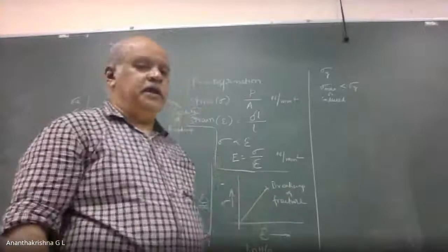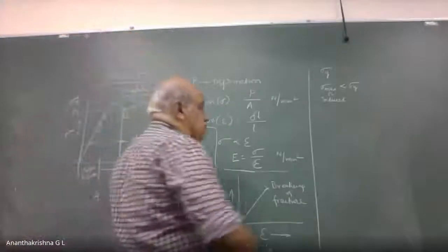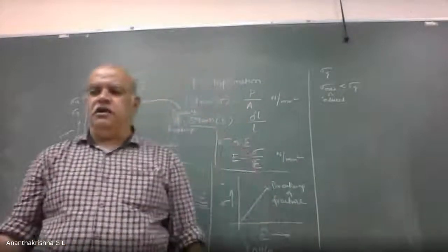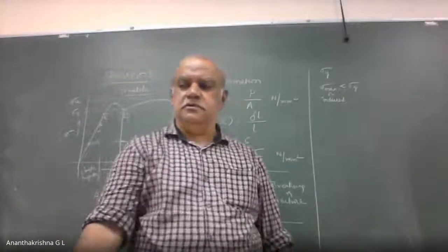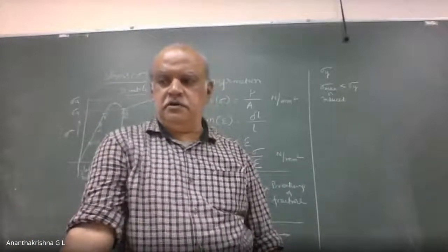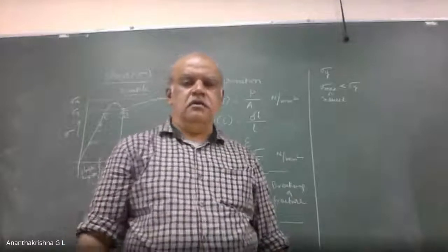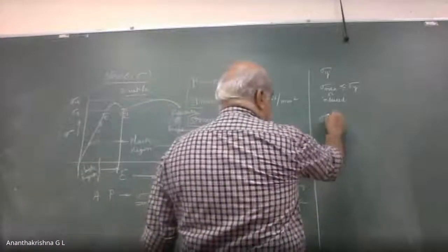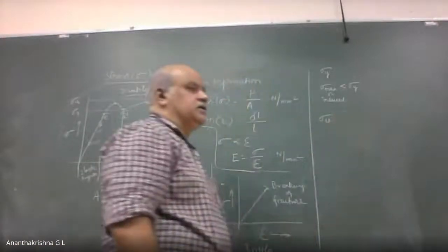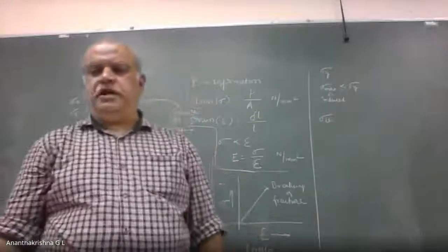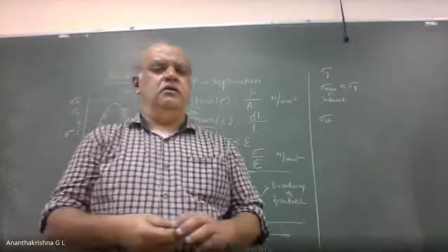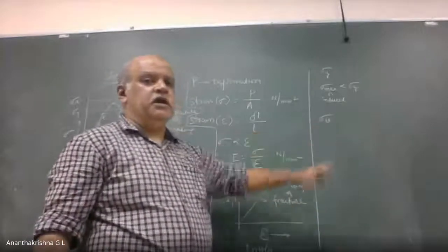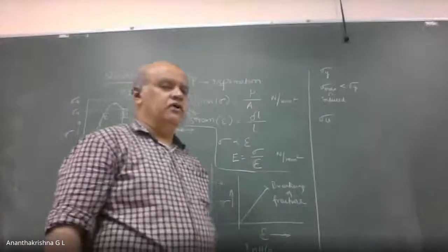Next, note down. For brittle materials, the ultimate stress sigma u of the material should be taken as reference for designing a component.